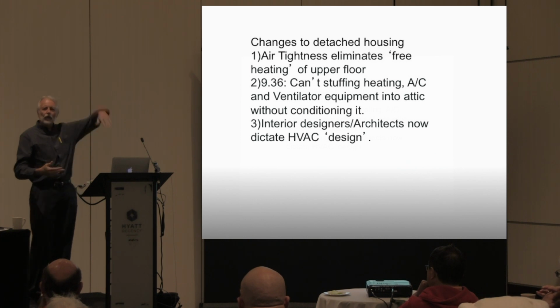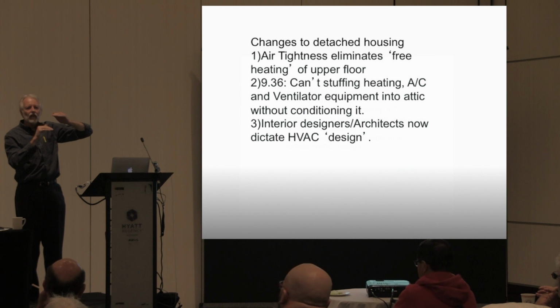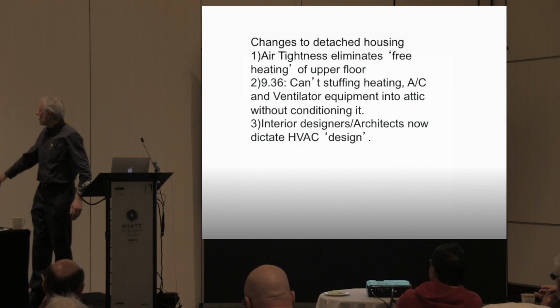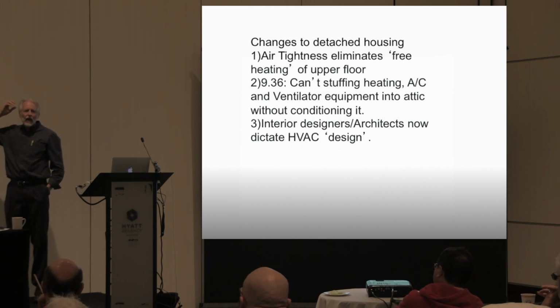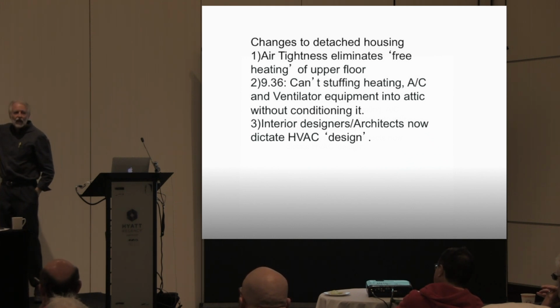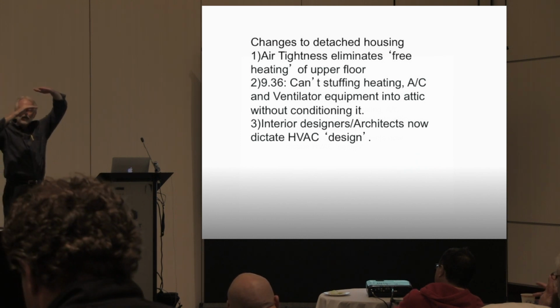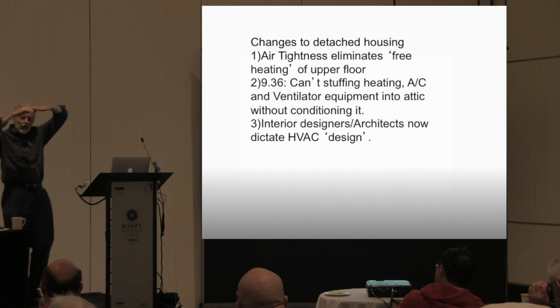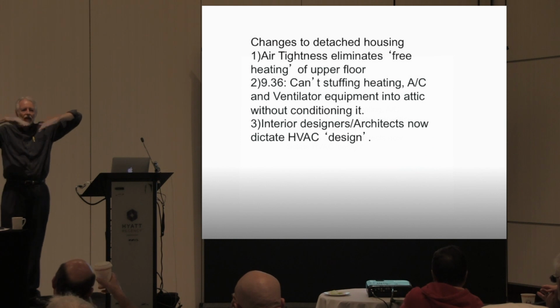But the problem is when you build a leaky house, remember, your thermostat is the only thing that the furnace listens to. If you have a thermostat here, this is the captain of the ship. That furnace will do anything in its power to keep this thermostat satisfied. It has no idea what's going on in the basement, has no idea what's going on in the bedrooms overhead. When you have a standard build house, your top floor is getting a free ride off the air that's exfiltrating from the top floor because it's getting a free ride on the furnace heating the main level.